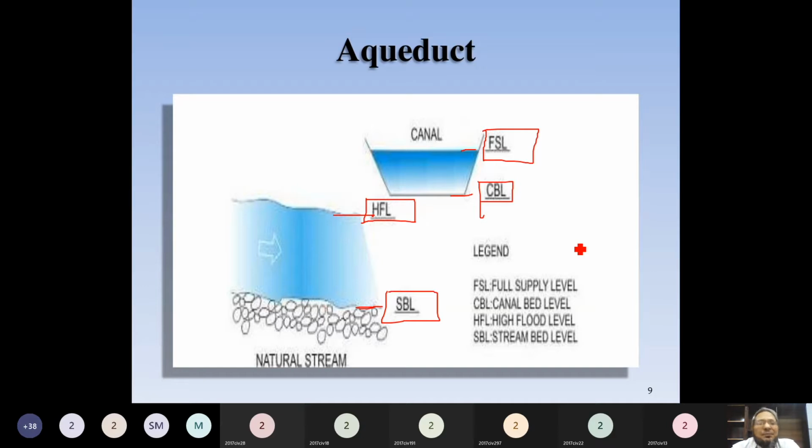So that may be a negligence, but normally we control and there are no floods. As far as you are saying that sometimes it breaches its banks, that is something else. For example, due to buffaloes and due to rats and rabbits, you know, they scratch the banks, and when there is a rainfall, then they weaken, and then maybe a piping starts, and the whole of the bank may be breached. So that is a separate story.